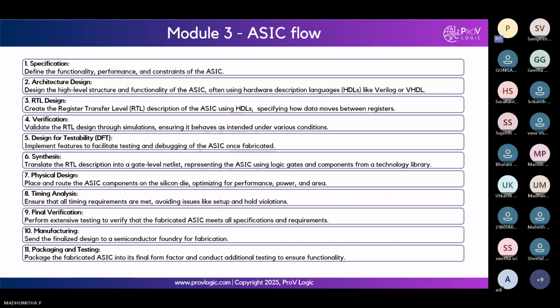So what we will do is we will run an entire timing analysis on the design that we have built, and we will check if the timing criteria or the constraints that were mentioned by the client are met or not. Ensure that all timing requirements are met, avoiding issues like setup and hold violations.